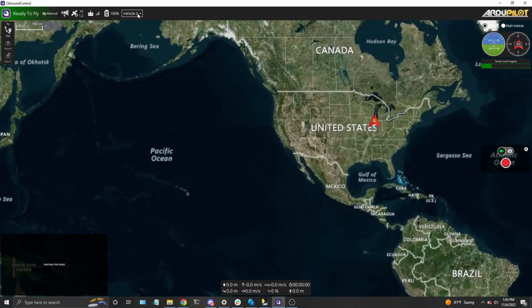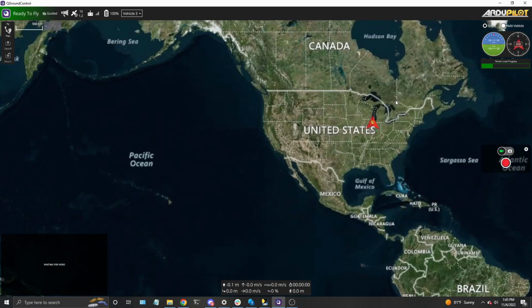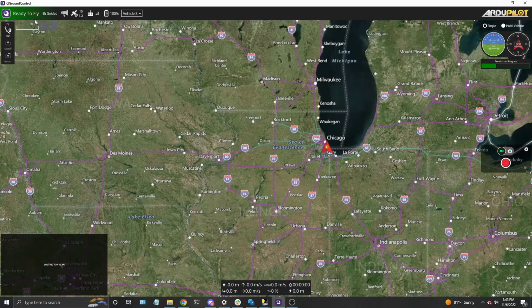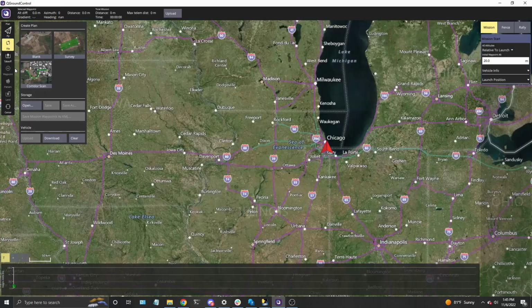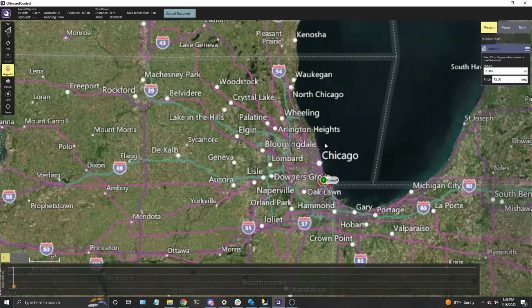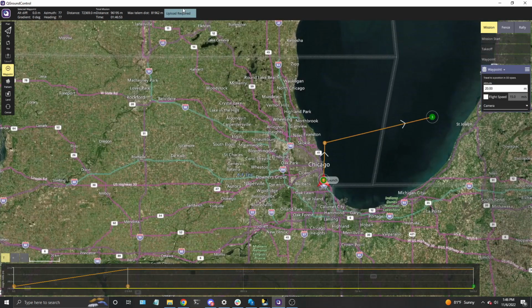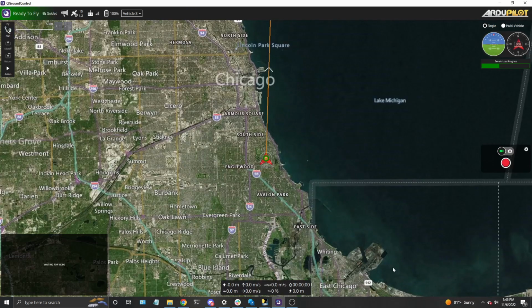So with vehicle 3, I'll set this to guided. Oh, actually, this is a plane. So the best way to take it off that I found is to create a mission. You'll have to excuse me because I'm not as familiar with ArduPlane as I am with Copter, but the best way that I've noticed is to upload a mission and then run the mission to get it to take off.